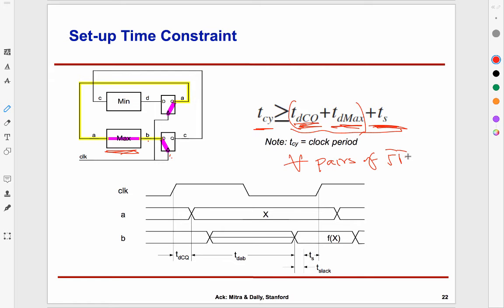I guess none of you are gamers, huh? Overclocking. And what do they do? They freeze the thing. They put their computers in a cooler environment, because cooling it makes it faster. So overclocking is enabled because by cooling it you are reducing the delay, and therefore you are reducing the right hand side, and therefore you can overclock.